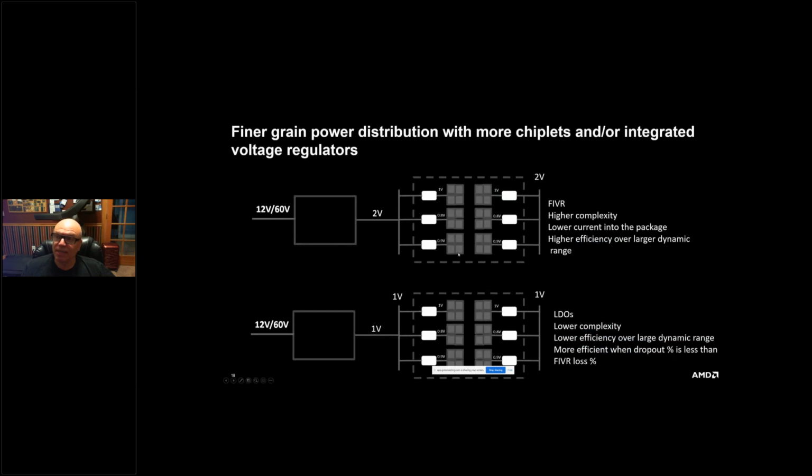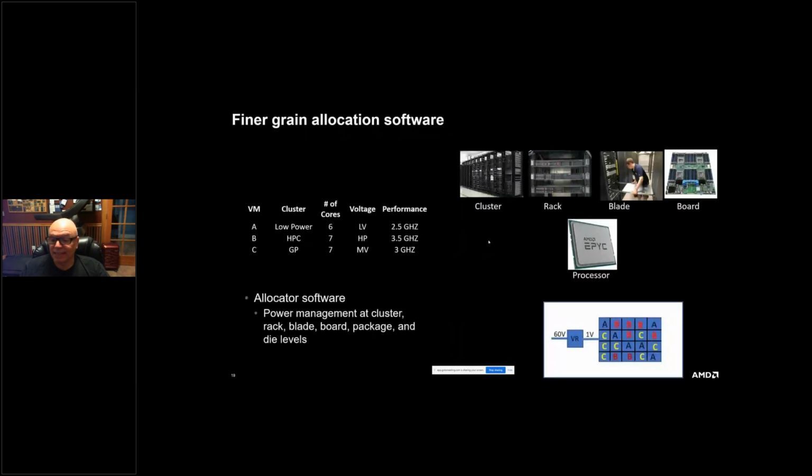Because when you break into chiplets, by the way, the power generally goes higher because you have all this interconnect between those chiplets. The area goes slightly bigger, again, because of the interconnect, the spacing, and all of that stuff. But overall, I think if you manage that well, you create an opportunity actually to make up, and actually significantly more than make up. Especially if you look at the data center level. Suppose you have that very clever, very smart software that actually uses exactly the exact code for the exact workload.